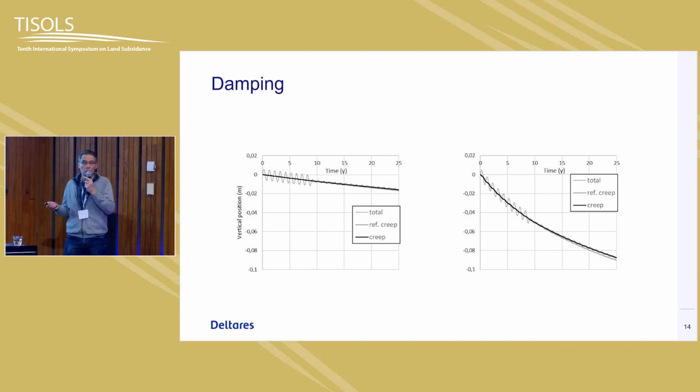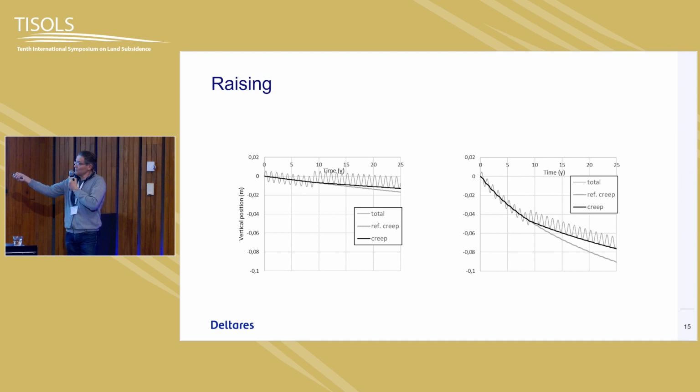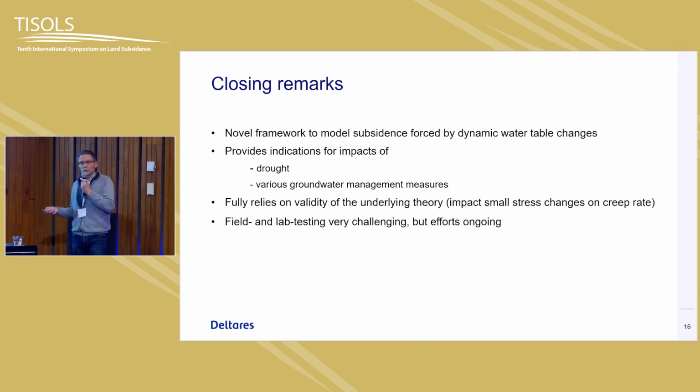This shows a similar result for the damping. Well, you tell me, do you see much difference? Not a lot, right? A small percentage on a couple of millimeters on the left. On the right, you see raising groundwater level. That's a major impact. If it's possible to do that, you'll get a response like this. That is just like an exploratory tool.